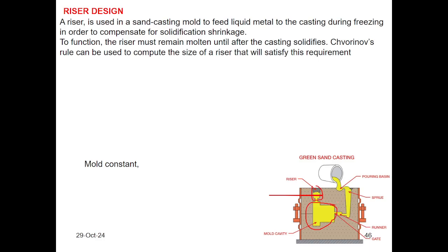But if the porosity is not adequate, then the riser is open to the atmosphere, and through the riser the air can leave the cavities. But mainly the riser is to feed the molten metal to the cast cavity while the material of the casting is solidifying.